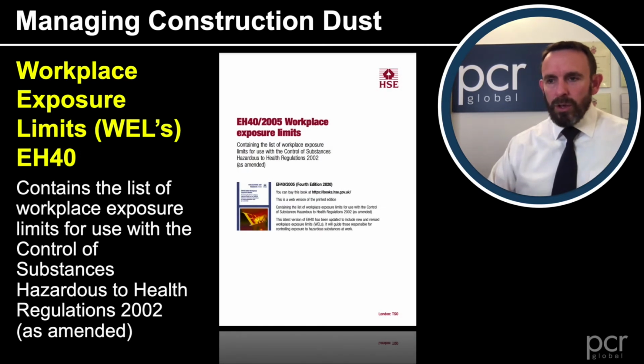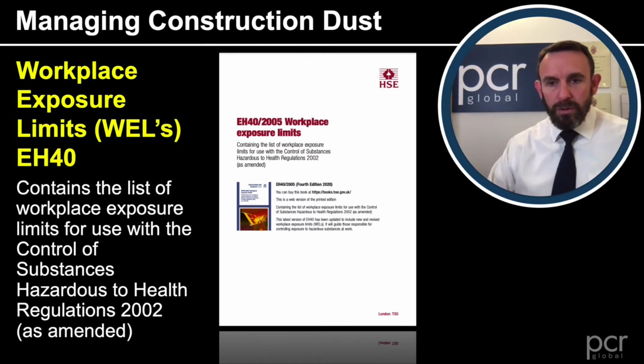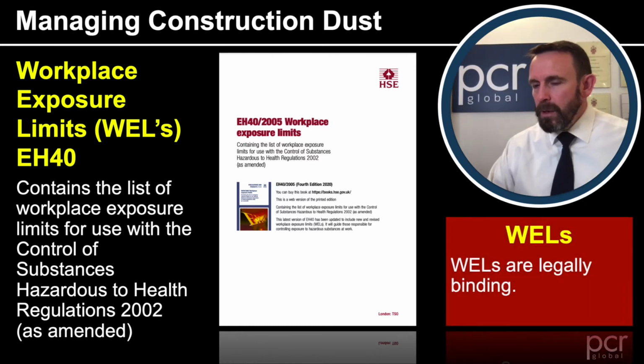So having a closer look at EH40, it is the HSE document, and it contains the list of workplace exposure limits for use with the Control of Substances Hazardous to Health regulations, the COSHH regulations. And what we must take note of is that WELs are legally binding, so where they are set, they must be adhered to.